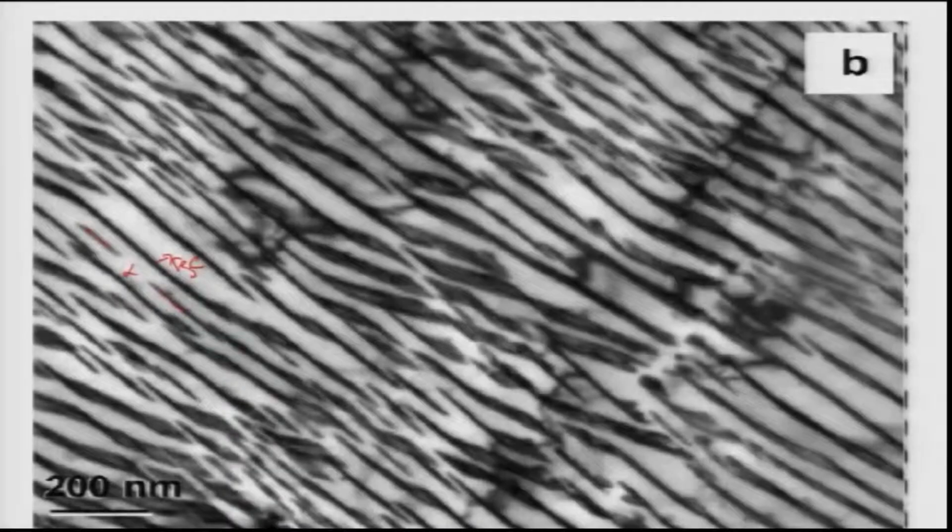As you clearly see, if you do the phase diagram calculations properly, then normally the volume fraction of the phases at about the eutectoid temperature for the 0.77 weight percent carbon alloy will be 85% alpha, and the remaining 14 to 15% is Fe3C. Now, if we know the densities of both phases, alpha and Fe3C, you can clearly see the ratio of the thickness of the cementite and alpha will be 7:1. That is possible to calculate. In fact, this will be one of the problems in your assignments, to calculate the thickness of these phases in the microstructure.